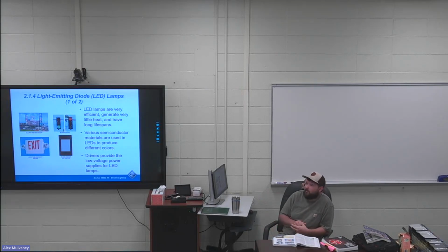Where you might have heard that if you turn on fluorescent lights, the worst thing for a fluorescent light is actually the act of coming up in power. It's harder on the lights. That's why a lot of times you see buildings where fluorescent lights are just left on, so that turning them on and off doesn't decrease the lifespan. But with LEDs, on and off does not matter. You turn them on and off 1,000 times, it doesn't increase or decrease the lifespan.